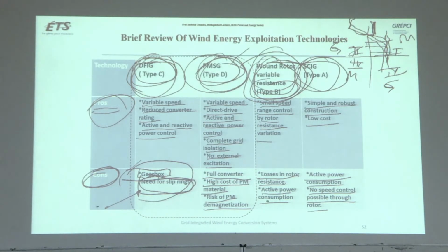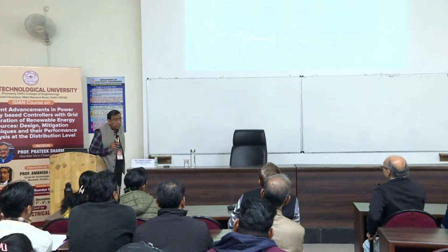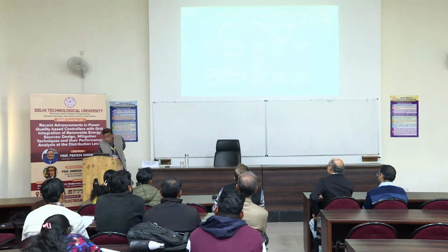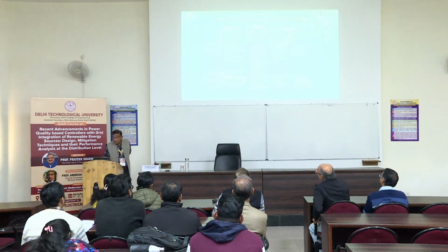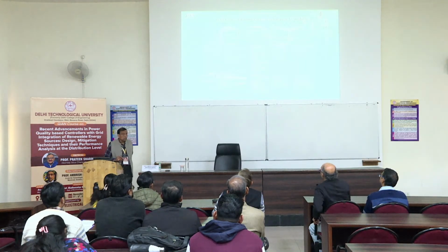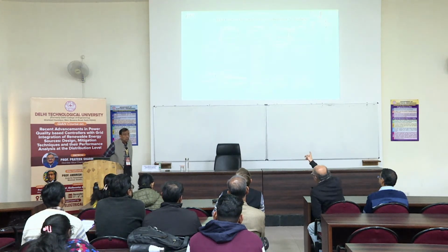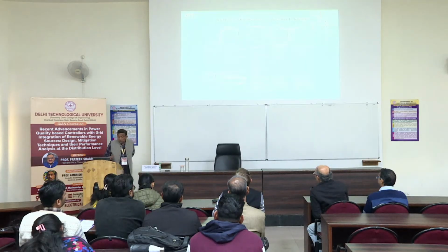Sir, in type D, complete grid isolation is possible. Where? Type D. PMSG, yes. Complete grid isolation is possible. But sir, why is it not possible in C? Because their stator is directly connected to the grid. You see?